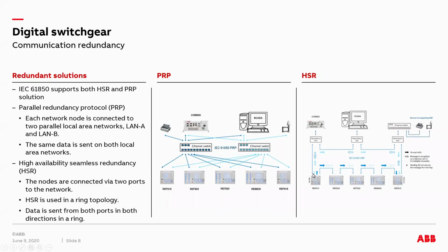So that means these communication ports are networked in a ring form, and the data from each device is sent in both directions. The same data is sent in both directions. Again here, the failover time is totally eliminated. If there is a network problem in one path, the data comes back to the healthy section of the network, and the process is taken care of.